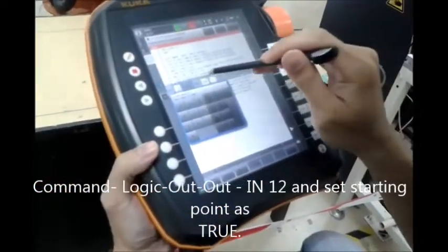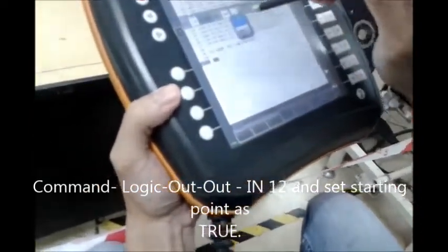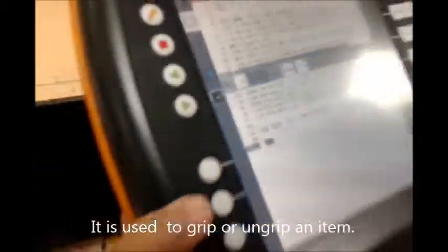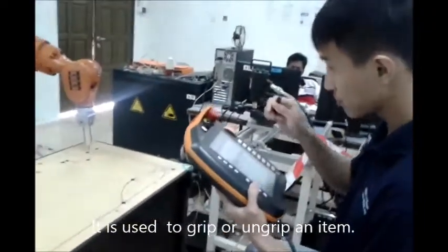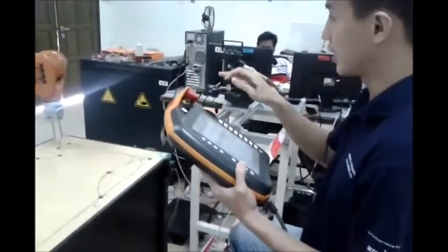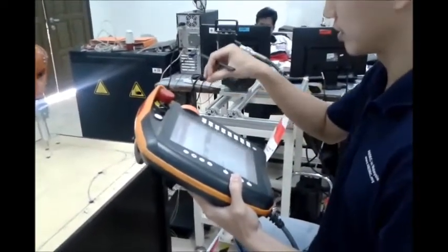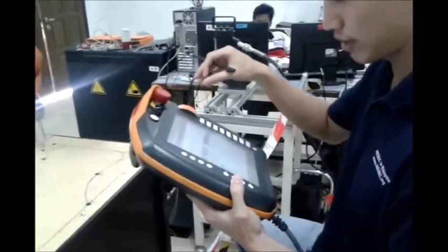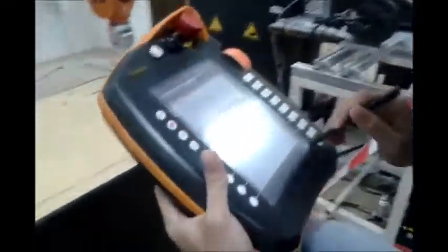Okay, then for the starting point it will be true, and this will be the blank. Basically, the out function for this sensor is to grip and ungrip a certain item with the end effector. When the out function is true, it means the end effector will grip the things, and then we key in the command and press OK.